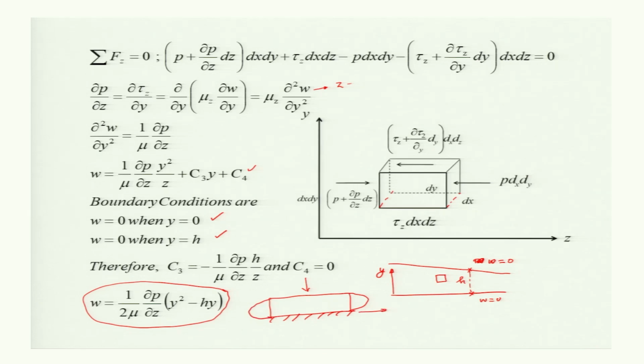This is the z direction, the axial direction of the bearing. So, along the axial direction in both ways, and this is the length of the bearing L, and this is your y. So, the flow will be in this way, and that is giving the side leakage.